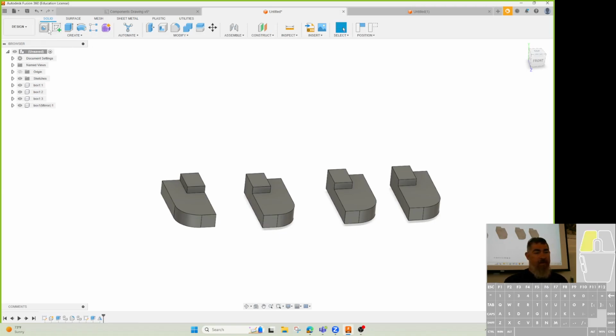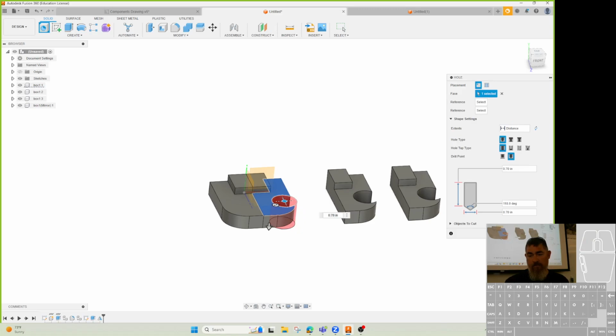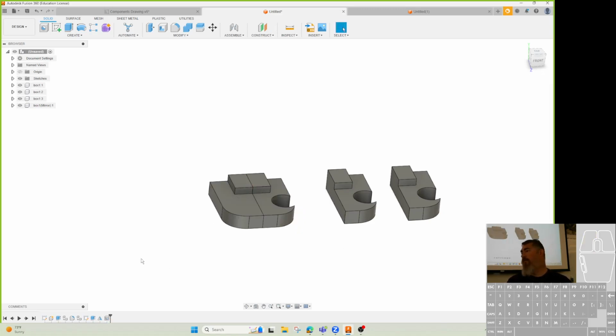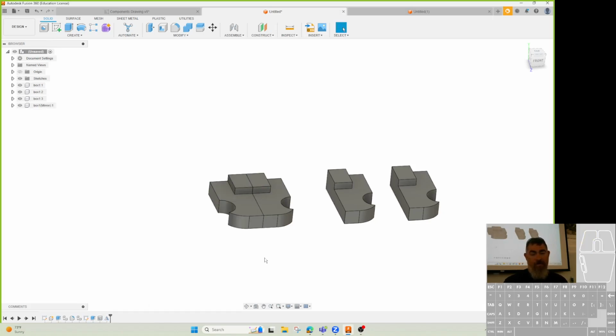If I do any changes now, it doesn't affect the mirror, because the change happened after the mirror. If I just go back in the timeline before the mirror and make a change, now I'll go back to after the mirror and the change is there. Is the mirror considered a new component? Nope, the mirror is the feature that's making that new component. Okay?